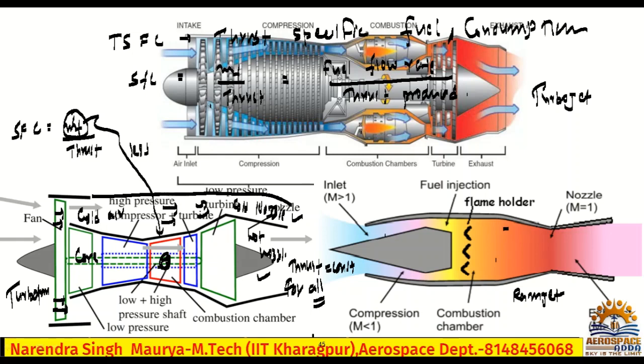To raise the pressure and raise the temperature. So if you are raising more temperature from the compressor and burning less fuel, you are getting the same TIT, 2000 Kelvin. If you take compressor help, then you can burn less fuel in the combustion chamber but get the same temperature of 2000 Kelvin at turbine inlet.